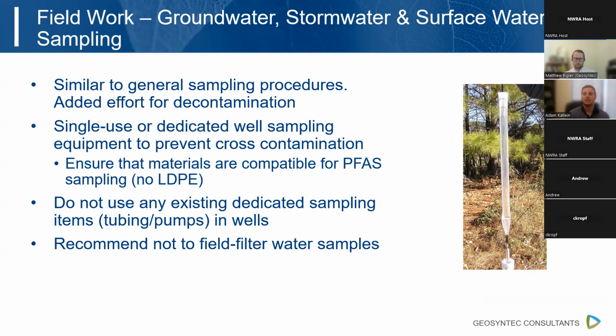Along with this, you're going to want to ensure that materials are compatible for PFAS sampling. No LDPE used out there. As I said, typically most vendors will have HDPE options, but just have to ask. And also a lot of sites that we've come across have existing dedicated sampling items such as tubing or pumps in the wells. This is similar to the driller tank where we just don't know the procedures that were used in the past. So we'd recommend not using the existing dedicated items in there. And finally, the recommendation is not to field filter water samples based on just the interaction of PFAS adherence to the filters themselves.